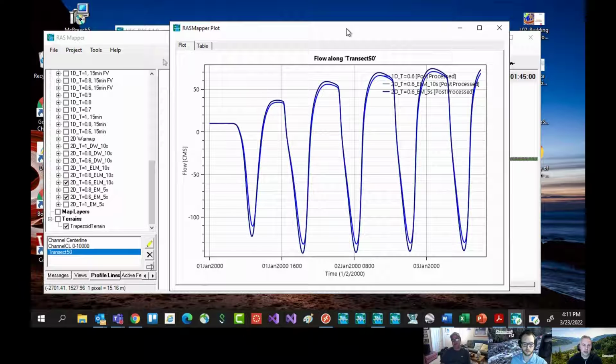And then what would you say, Gary, would be the most important things when you're thinking about doing a tidally based model in an estuary? Well, first of all, you got to have your boundary condition. If it's ocean driven, I like to put my boundary condition out in the ocean, and I like to have my terrain start at ocean level and then come up, because then you get that wave propagating up and down, but you also get a convergence of the terrain vertically, and that'll help capture the velocity acceleration that occurs when that wave comes in. So that'll give you more accurate velocities coming in.